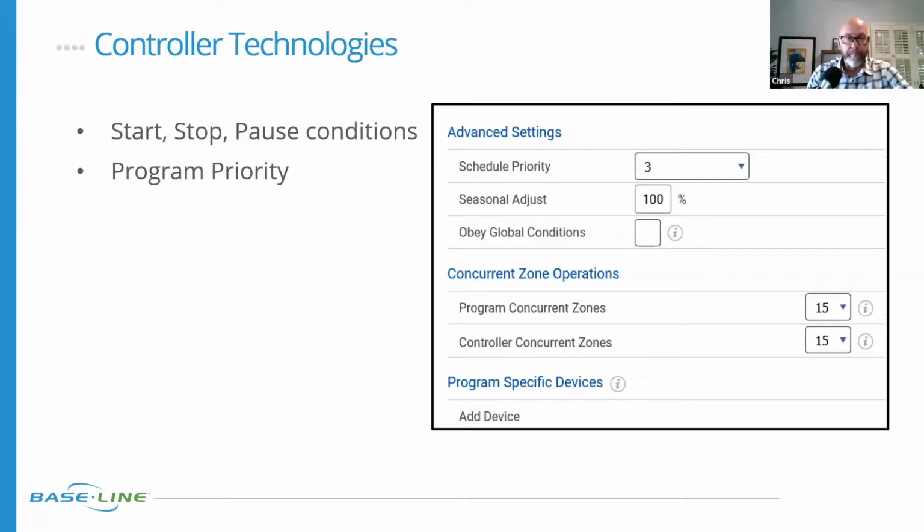Right. And you could do that by having one program, those more important ones, in a higher priority program, and make sure that those get water before the other lower priority programs water. Absolutely. Yep. And normally I advise, when I bring up program priority, to use them with a purpose. Don't use them just for fun. This is a very dedicated purpose. And I think this fits exactly what program priority suits well for. Definitely. Yep.